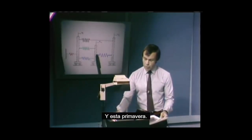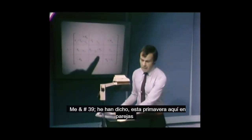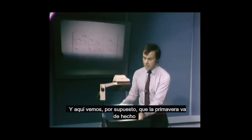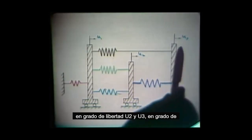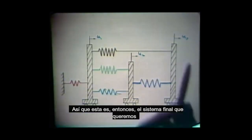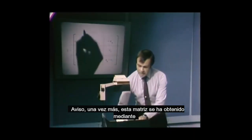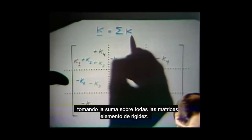This means here we are having U2 and U, sorry, this spring, I should have said, this spring here couples into column 2 and 3, meaning U2 and U3, and here we see, of course, that the spring indeed goes into degree of freedom U2 and U3. So this then is the final system that we want to analyze, and this is the final stiffness matrix that we had to obtain.